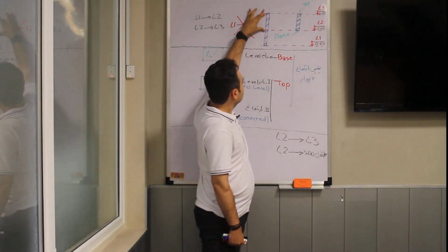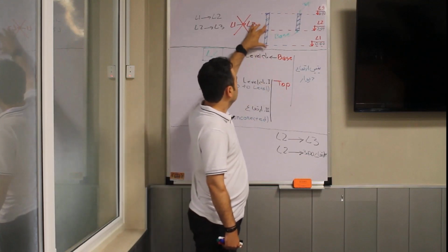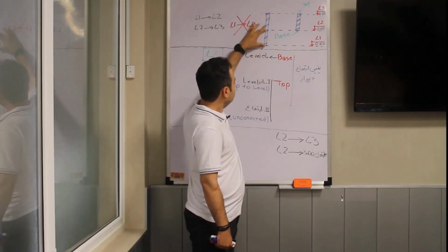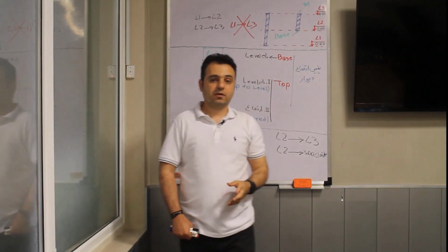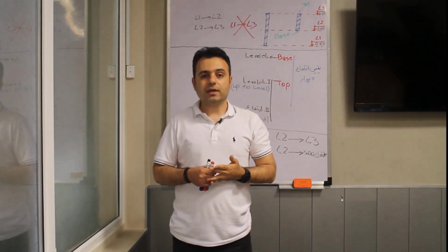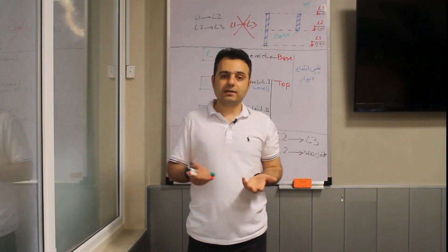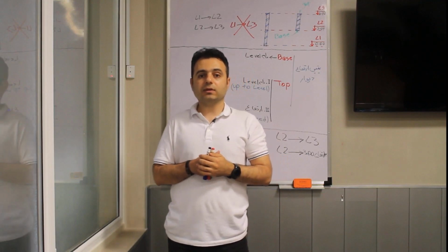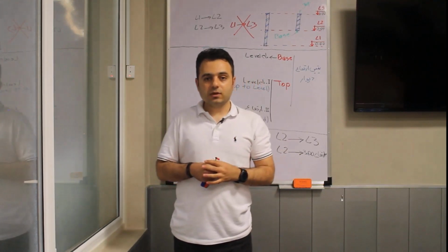So it considers the volume of the wall in the next floor in here too. But if you draw these two, for example, separated, each of these will have their own volume. And that's why we always draw the walls separated in Revit, even if they are repeated completely equally.